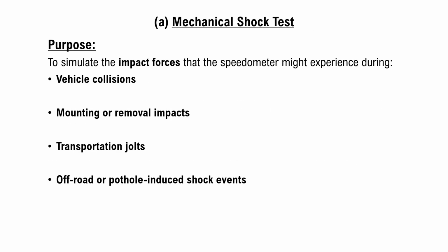To start with, the mechanical shock test. What is its purpose? To simulate the impact forces that the speedometer might experience during these four situations: vehicle collisions, mounting or removal impacts, transportation jolts, and off-road or pothole induced shock events.